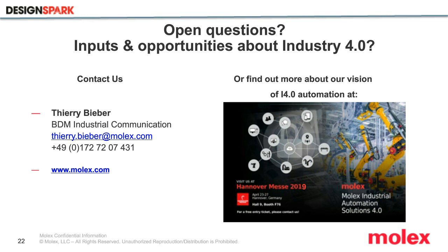I think NAMUR, which is an organization in charge of process automation solutions, is currently defining an architecture mainly for data collection and data analytics, acting as a data diode, meaning it is only able to get information from the process into the cloud and not interact in the reverse way.